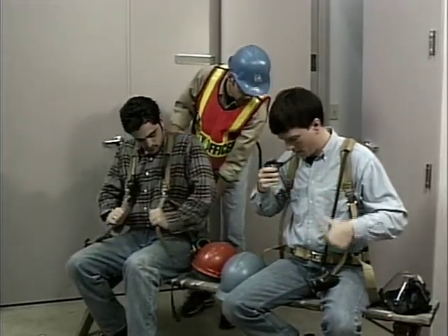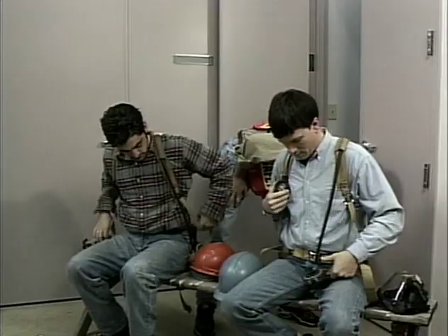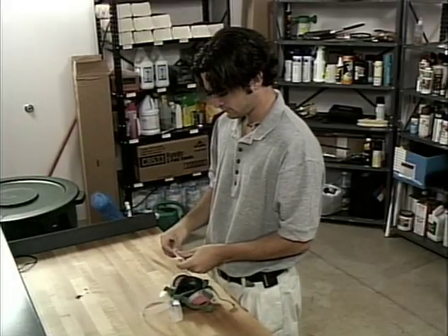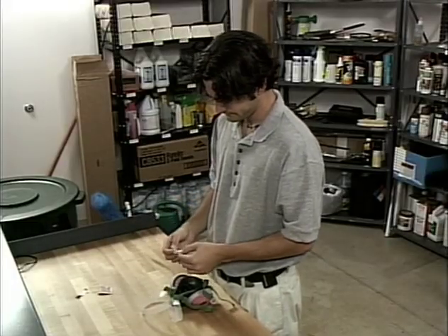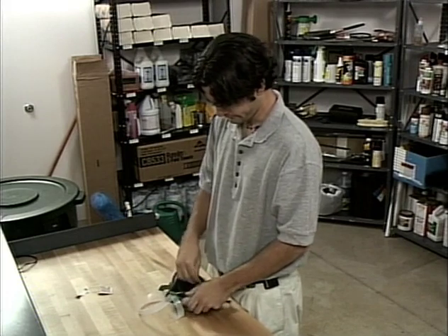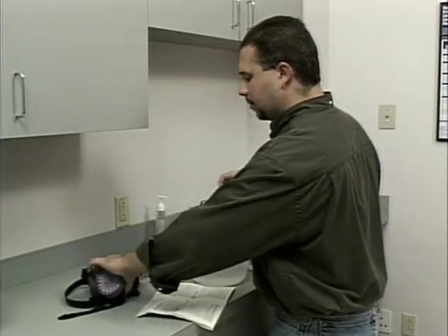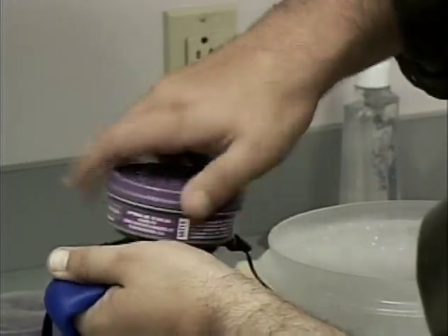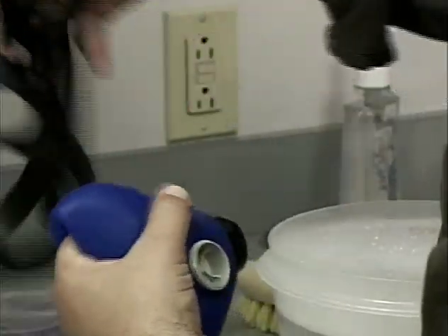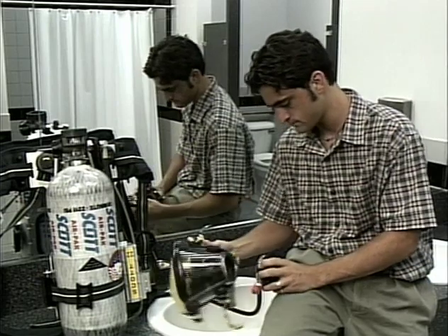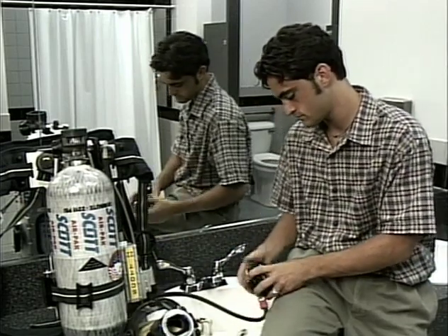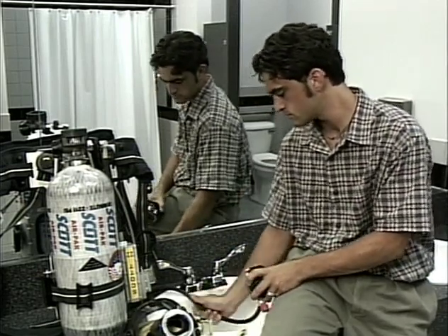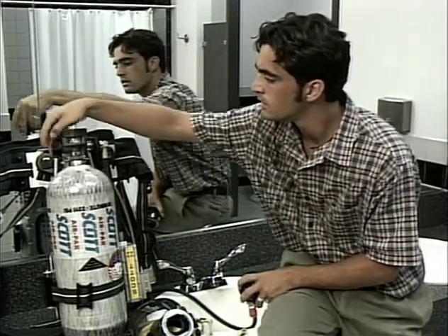Proper care of your respirator is essential. Following recommended cleaning and disinfecting procedures will keep your respirator and you in good working condition. The OSHA-approved cleaning procedure begins with removing all filters, cartridges, and canisters. Next, remove the straps. If your respirator uses hoses, check them for defects. This goes for the valve assemblies too. If you find any defective pieces, repair or replace them immediately.